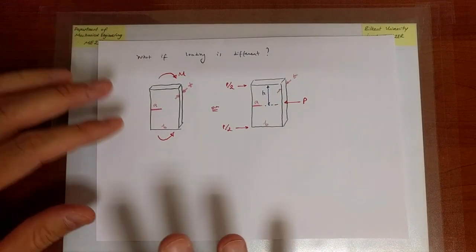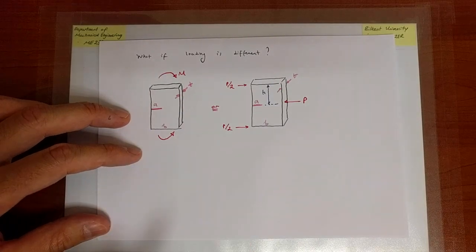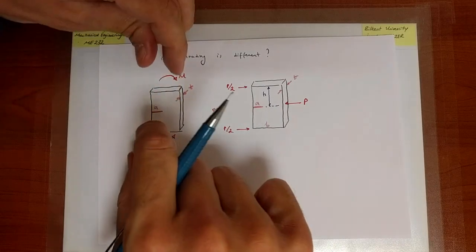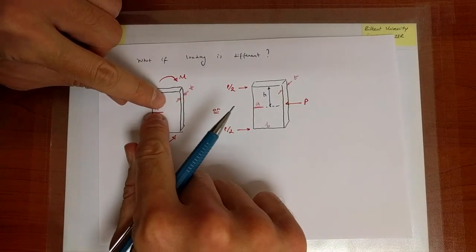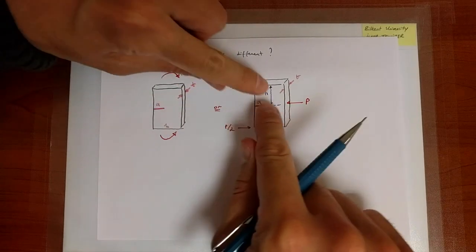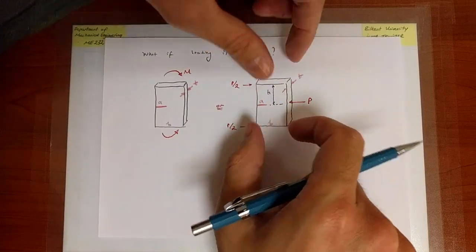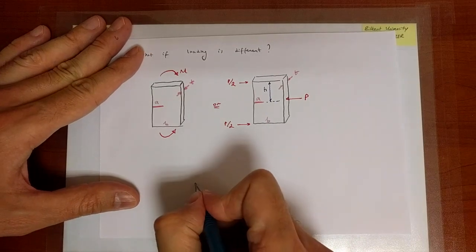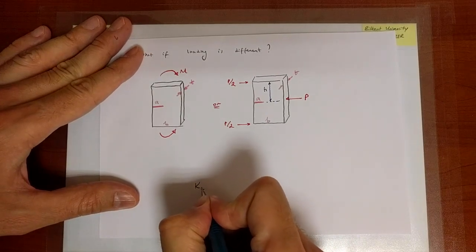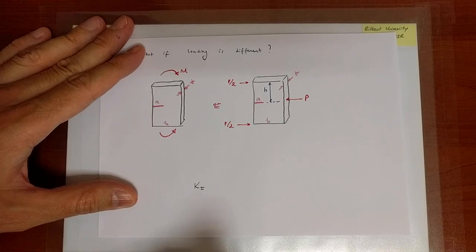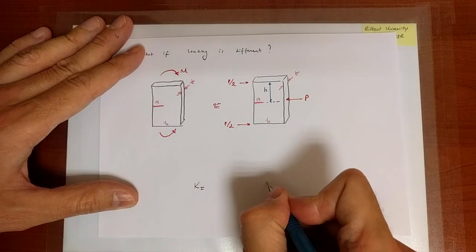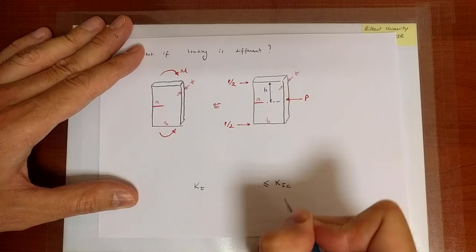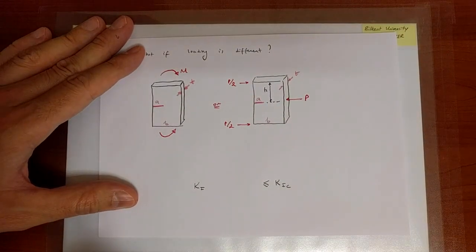So first of all, what is the criterion that we need to employ? Now, in both cases, I have a bending type scenario, and in both cases, due to bending, the crack faces will try to move away from each other, right? I try to bend in this case as well, so that's an opening mode. So I'm looking at K1. And the criterion is always to take K1 and compare it against the fracture toughness, K1C. Okay, that's our failure criterion.